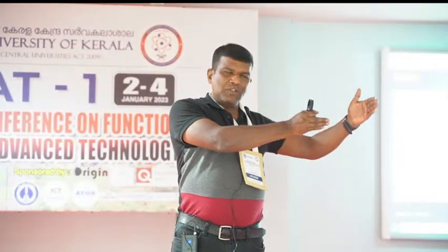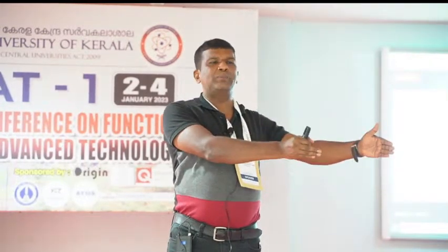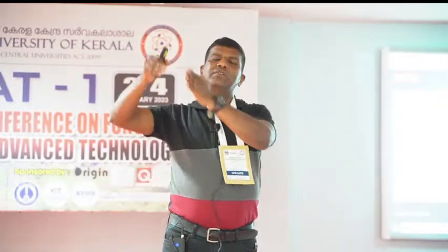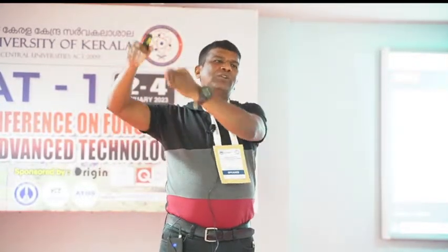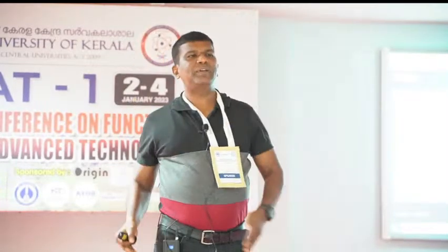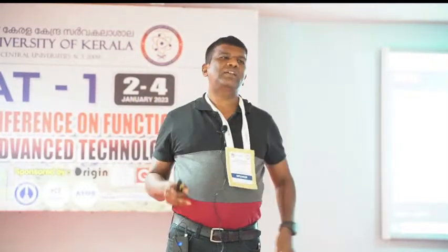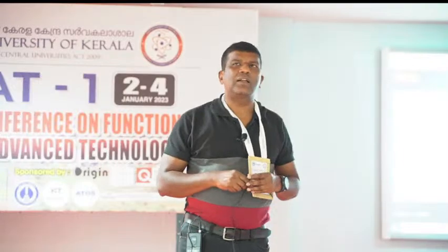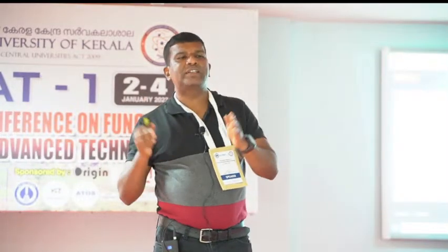Now, if you choose the frequency not at 15 or 17 kilohertz, but at the contact resonance, your signal will get amplified. But the problem is, the moment you work at contact resonance, not only your signal, but also the topographic signals will combine with the PFM signal.